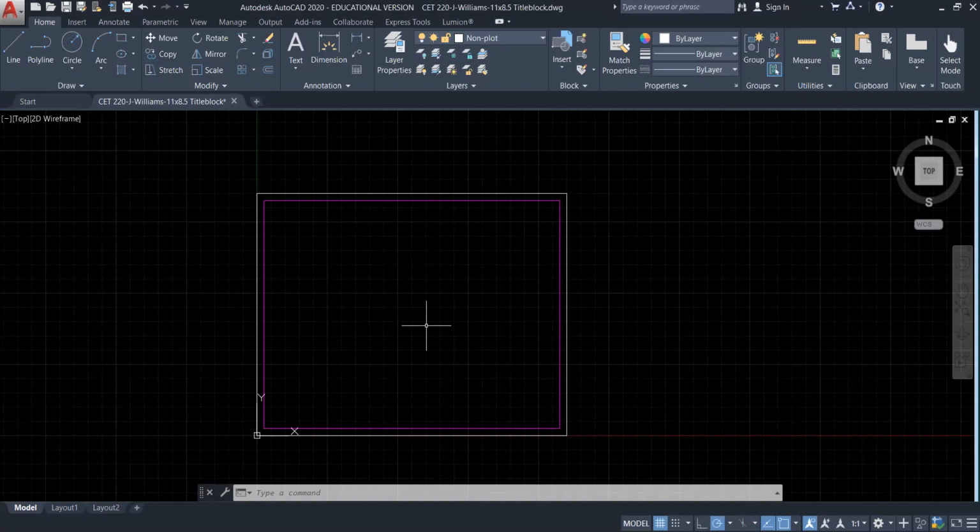That's going to be particularly important when you start to insert objects from another repository into your drawing. When you use an insert tool, they're typically going to come in as one entity or a block, and sometimes you will have to explode them to manipulate them. All right, so now we've exploded that polyline.